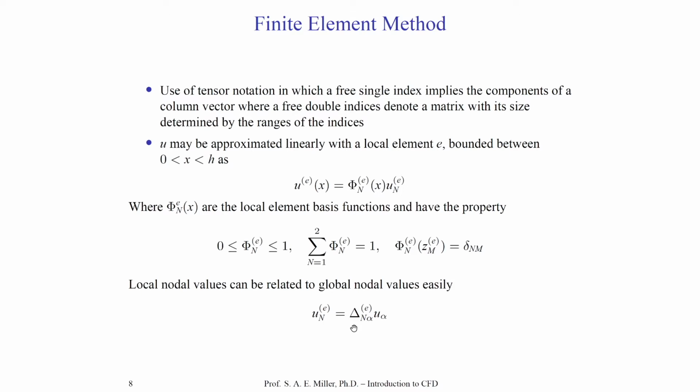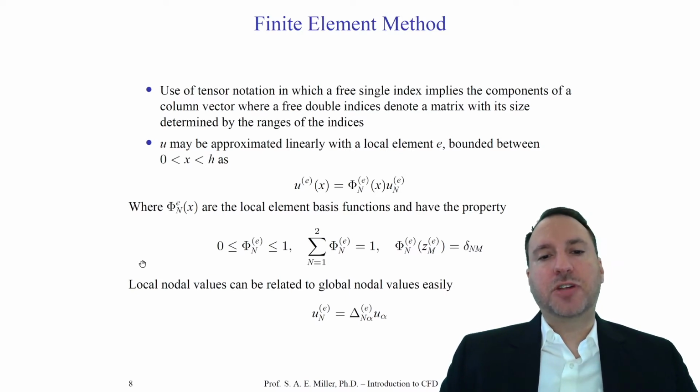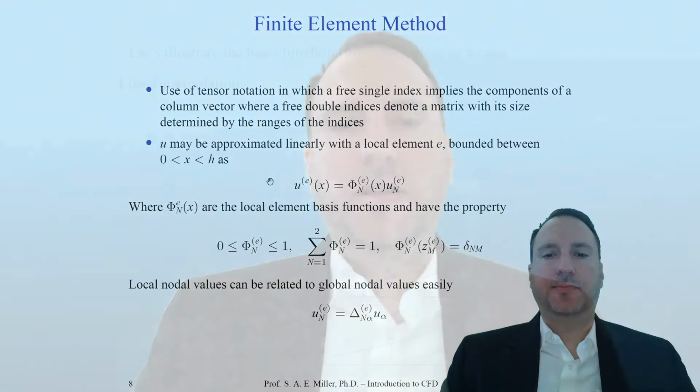You can see now we've shown the major picture of the Galerkin finite element approach: we're taking our domain, splitting it up into elements, then we form basis functions, which are chosen by us, it's our choice, which have these certain properties. We then find the solutions on each particular element, given the boundary conditions and connection between each element, and find the solution based on the basis functions and reproject it back to the global domain. That's the process of the finite element theory in a nutshell. Let's now look at some basic basis functions.